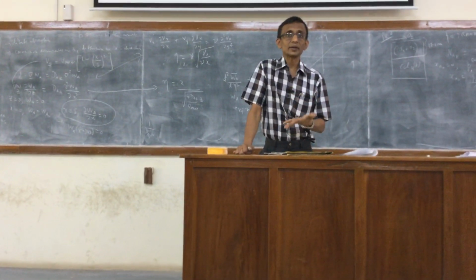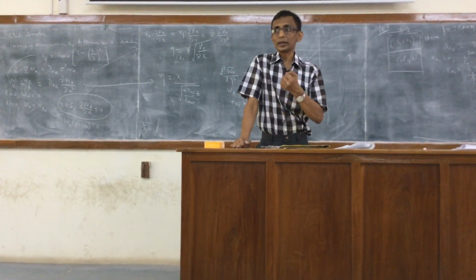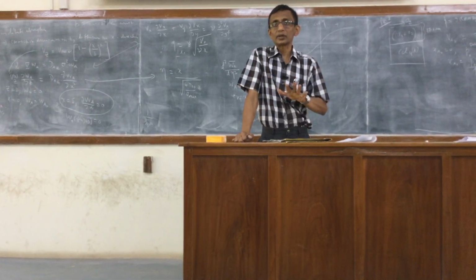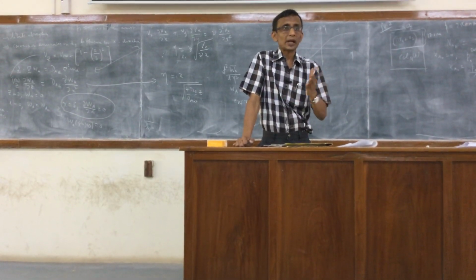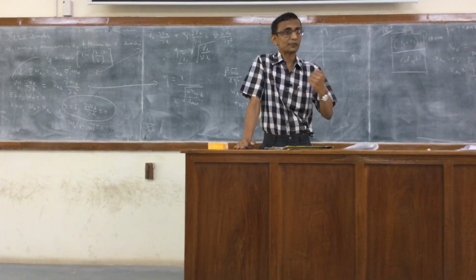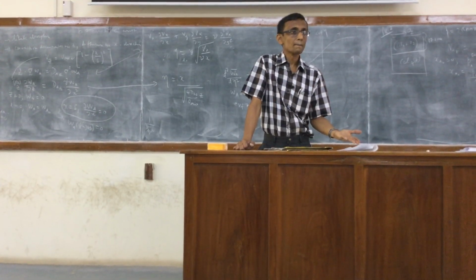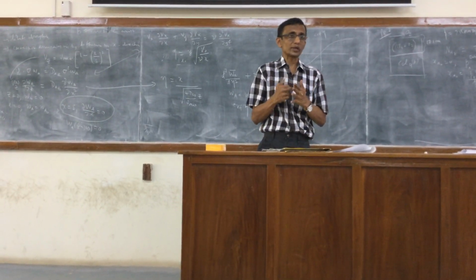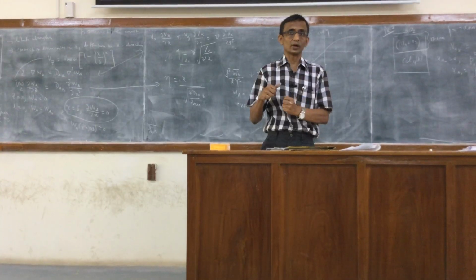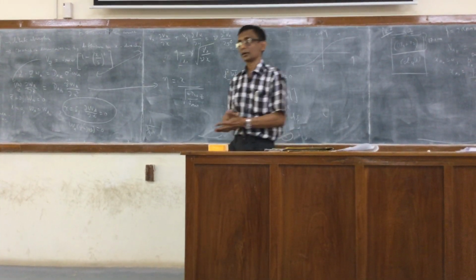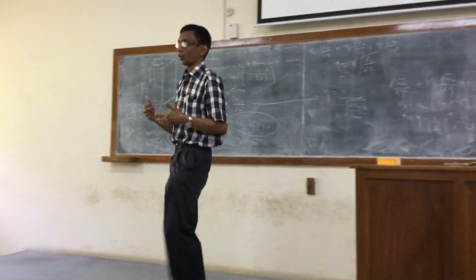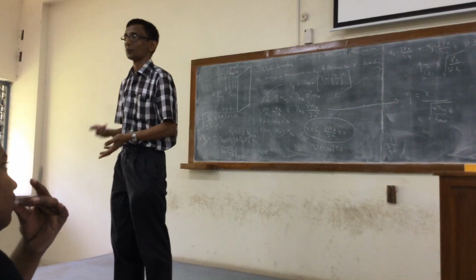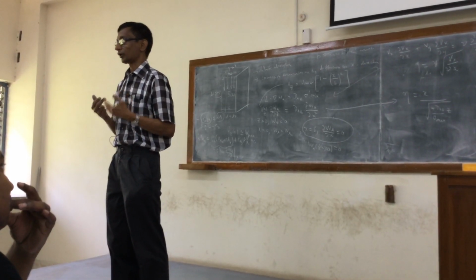So that's something that we keep avoiding. If you want to really confront having to calculate the velocity without having to bring in Fick's law, then you have to propose a momentum balance for each species, and those equations have to be solved along with the continuity. When you are trying to do just with the continuity equation, you need this Fick's law, which is itself very approximate, right? And then we don't know how to handle the velocities directly, so we always have to make some approximation, like it's a stagnant film, or it can be neglected and so on and so forth, right?